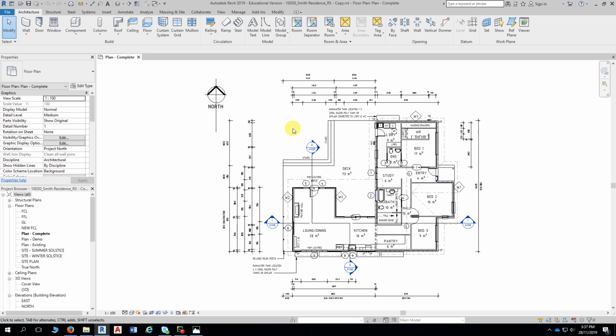It's not something that I would suggest that you do ordinarily, because it is quite a drastic thing to do, because there may be objects or aspects of the project that are not in use that you may need to use in the future if you come back to this project. If you actually purge them or eliminate them, they're gone for good, unless you reload them as families. We're only doing this essentially to get the file size down so that it can go up to Learn. And that's why we purge.